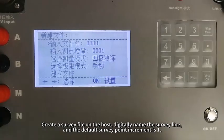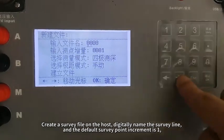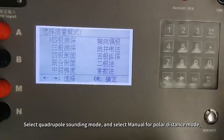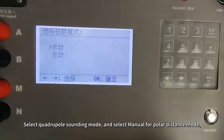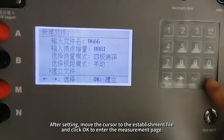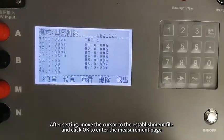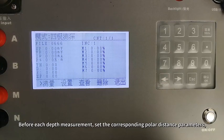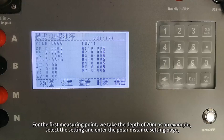Create a survey file on the host, digitally name the survey line, and the default survey point increment is 1. Select quadruple sounding mode, and select manual for polar distance mode. After setting, move the cursor to the establishment file and click OK to enter the measurement page. Before each depth measurement, set the corresponding polar distance parameters. For the first measuring point, we take the depth of 20 m as an example.